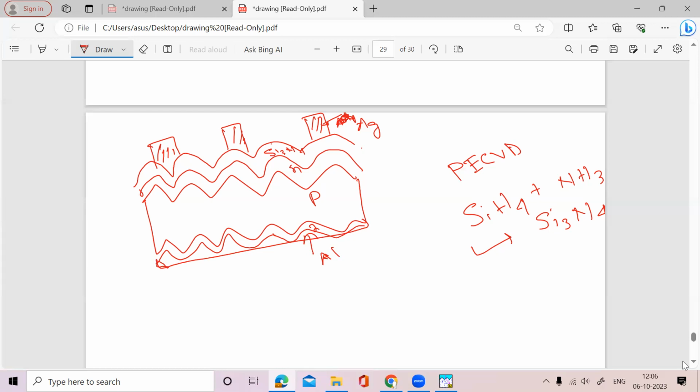What is the problem now in my device? First problem, on top there is a finger. It is called finger actually. In the finger, metal contact after dielectric, electron will not transport. In the back, already one junction is there. Now we have to do what is called firing. Firing means thermal shock. I have to give a high temperature thermal shock.